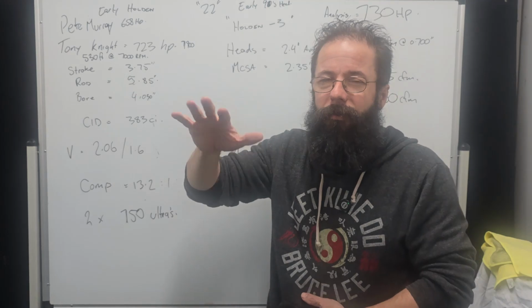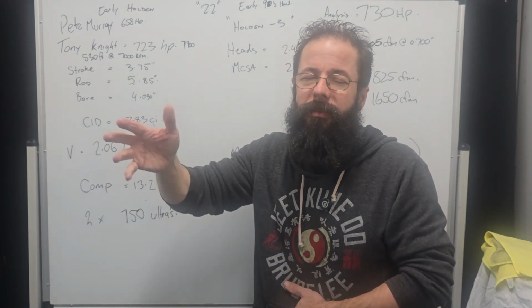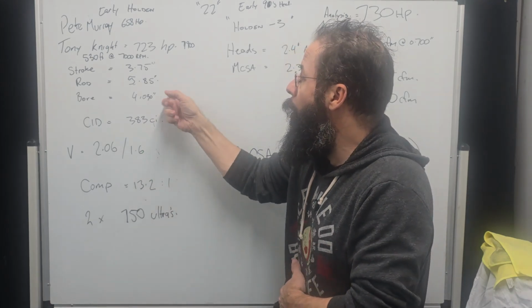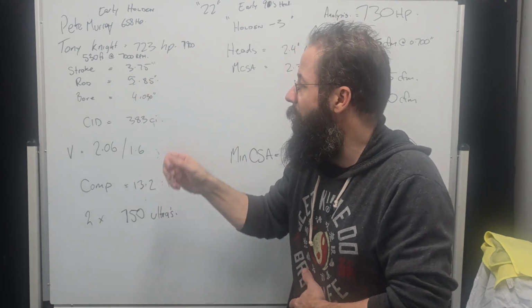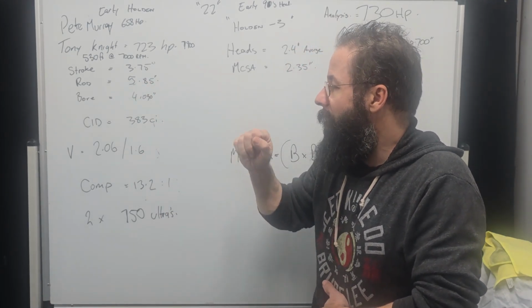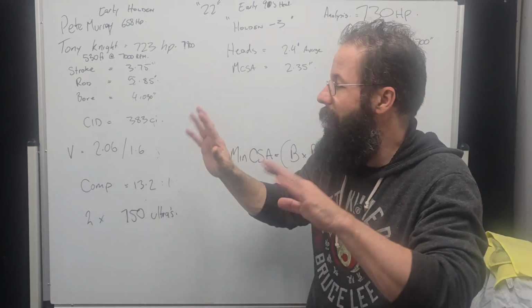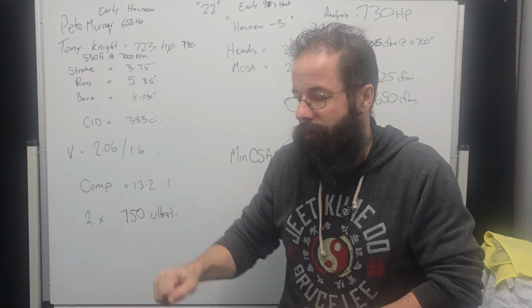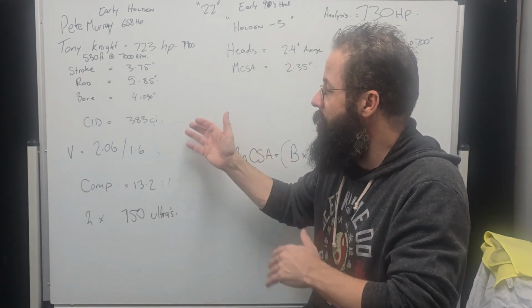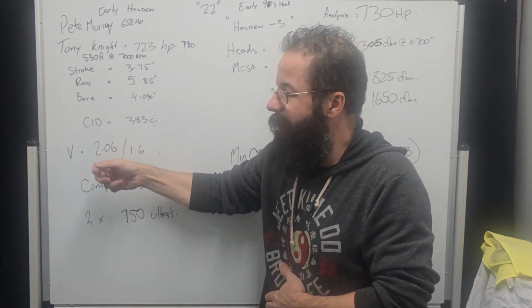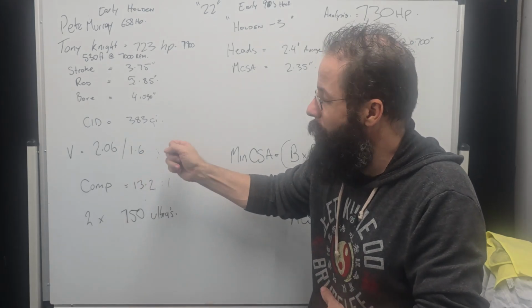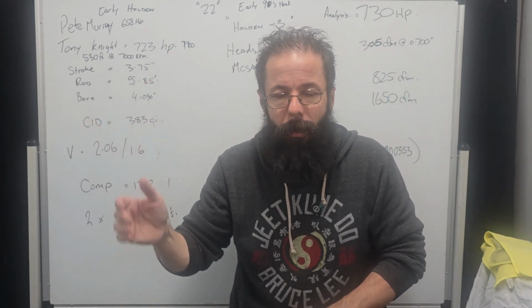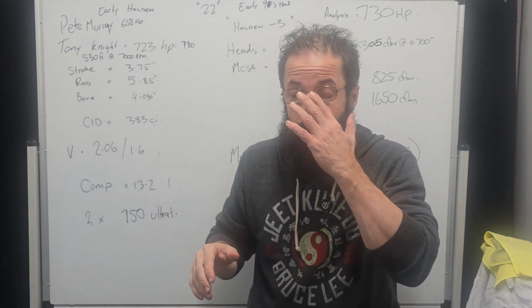Again, the Holden's like 5.650 something. Someone can put it in the comments. We generally always run a 5.7 or a little bit longer on a 5.85 on these. Bore 430 or 40, somewhere around there. I don't remember the exact bore. Cubic inches around 383. So it's like 381, 382, 383, something like that. And really, really good valve choice, 20616.